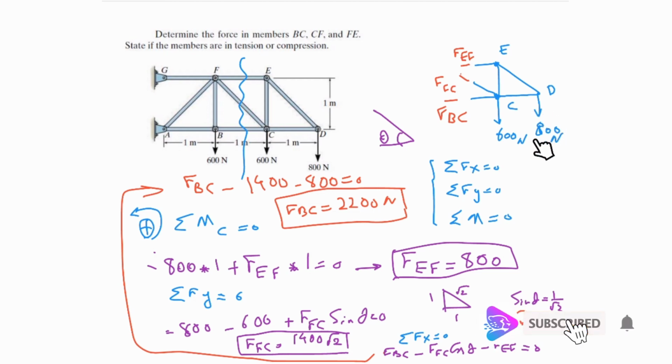I have three lines over here and two forces over here. I would say you can put whatever directions for these. Whenever you solve this, you get some values. If the value is positive, meaning that the direction is correctly selected. If it is negative, you change the direction. That's the idea here, okay? But it is possible to put the directions to get the positive values.